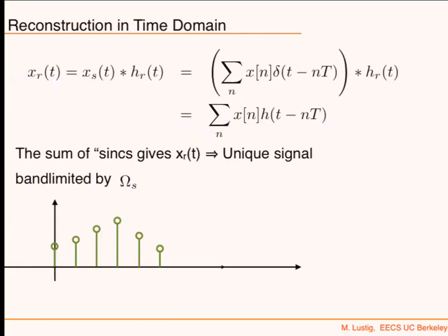Okay. What else did we talk about last time? We talked about reconstruction in the time domain. In fact, your ideal low-pass filtering is a convolution with the inverse Fourier transform of that low-pass filter, which turns out to be a sinc. It's just a shifted sinc, and so when you convolve impulse functions with a sinc, you get sincs that are translated and scaled by those impulse functions.